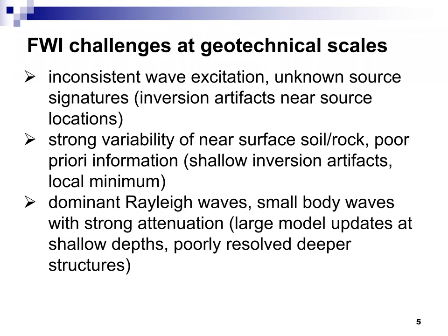We'll see what water does to us, but now you could be generating mainly shear waves at depth too. It'd be shear and P, but the P is going to be mainly influenced by the water, at about 1500 meters per second. We're not in real stiff rock or anything. Okay, yeah. I'm sorry, just a thought.